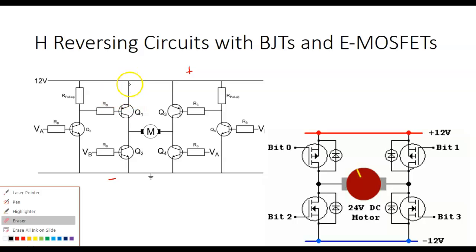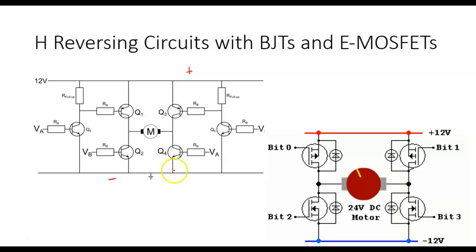electronically. So now we would bring, of course, I'm drawing from positive to negative, but you can see what I'm doing. I mean, I can go the other way if you want to. Then we get this one, and then now we're going through this guy, and then we'll go up through that one. This is called an H bridge control. We could do this with a programmable controller. Well, that's not true. It would be hard to do with a relay output. So this is one way electronically we could reverse a DC motor.